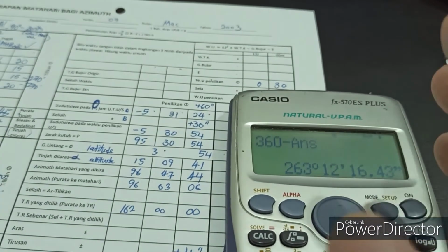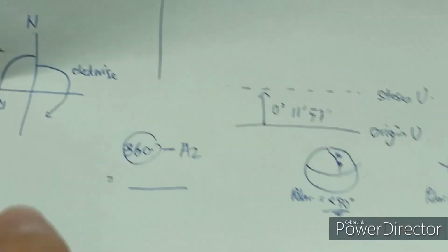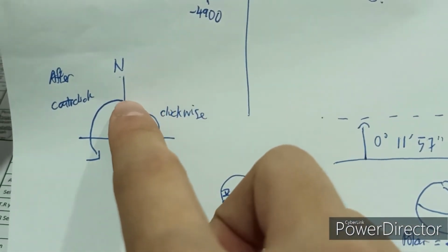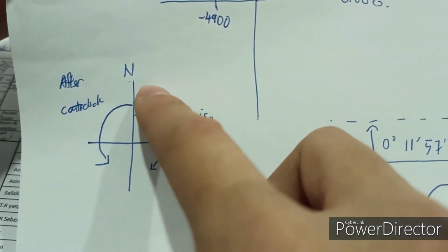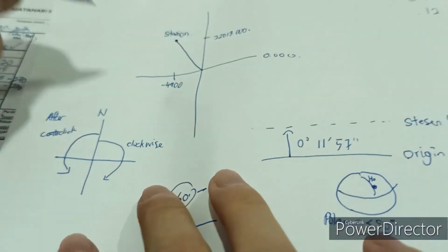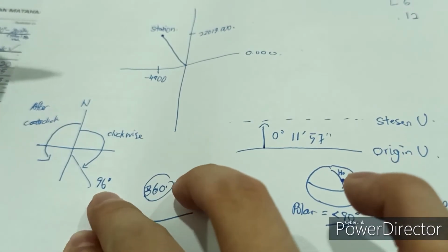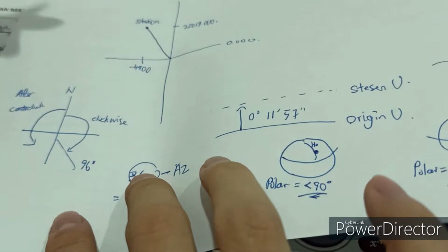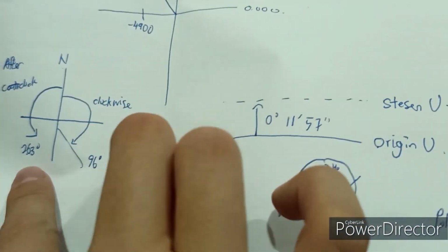Since it is the afternoon sun, we have to calculate it in a counterclockwise direction, while the morning sun we count in the clockwise direction. So this is an example. You just now got 96 for the azimuth. For the afternoon sun, we will get 296. This is the azimuth for the afternoon sun.